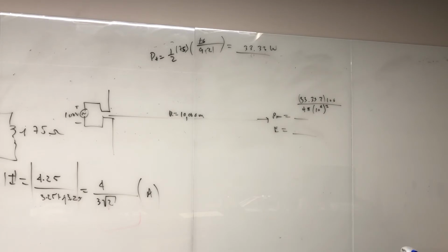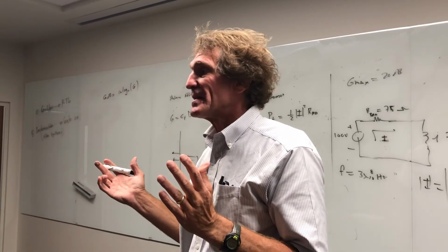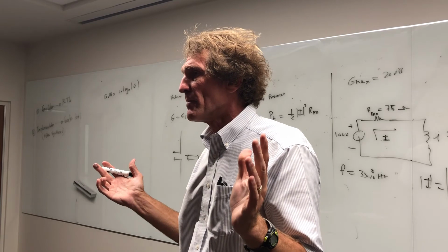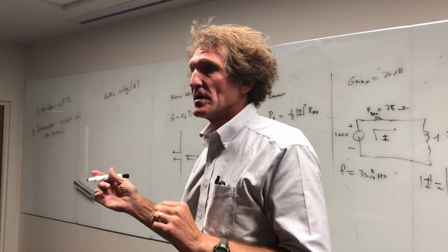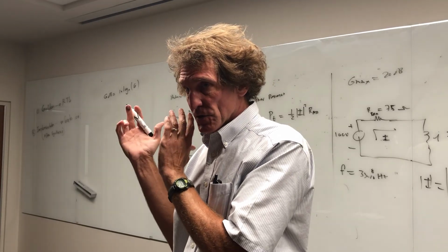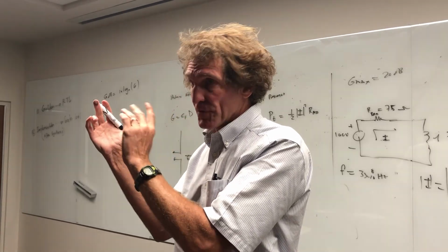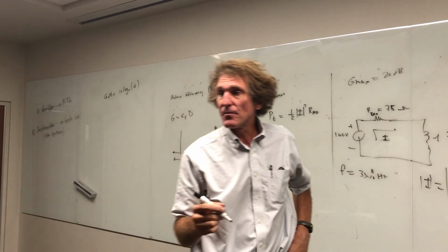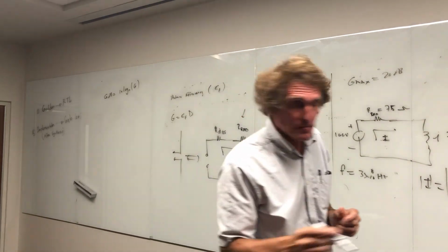With power, it's 10 log base 10 of a number, right? When you talk about dB power. If you talk about dB voltage, I think you've had this, maybe you haven't, dB voltage is 20 times the log of a linear term. dB current is 20 times the log of that. We'll talk more about that later, but you need to be familiar with this terminology, dB.